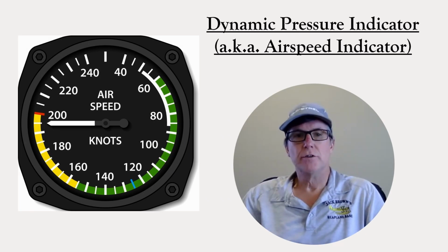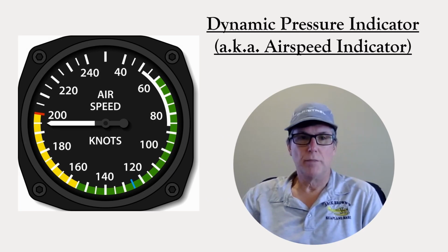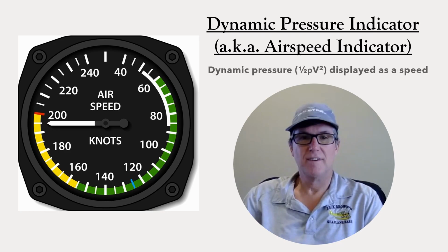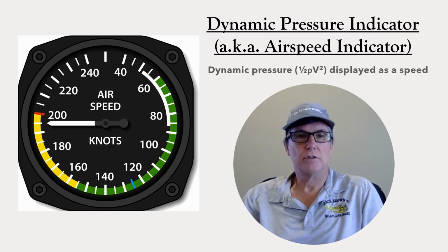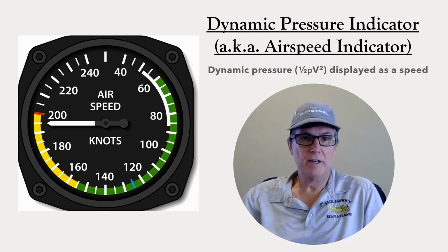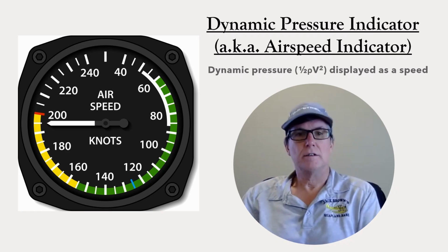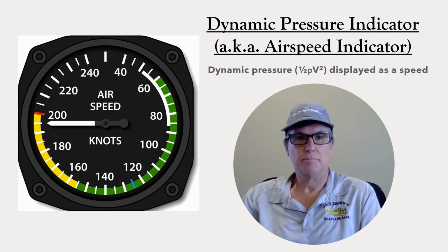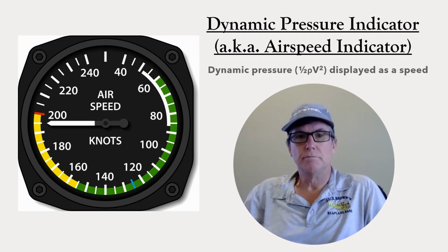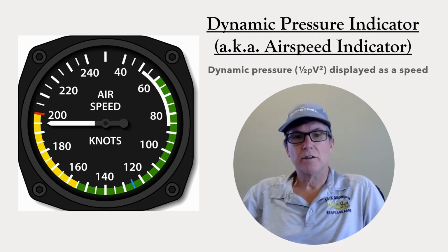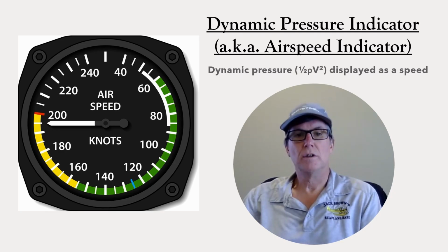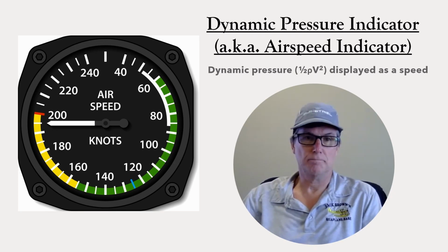The airspeed indicator measures the dynamic pressure by comparing the pressure at the pitot tube to the pressure from the static port. Dynamic pressure is a function of the airplane's speed through the air and the air density. The dynamic pressure is converted to airspeed assuming a standard sea level air density. Stall speed, as well as some other important speed references, are influenced by air density in the same way that dynamic pressure is. So this indicated airspeed is more useful than true airspeed for maneuvering the airplane.